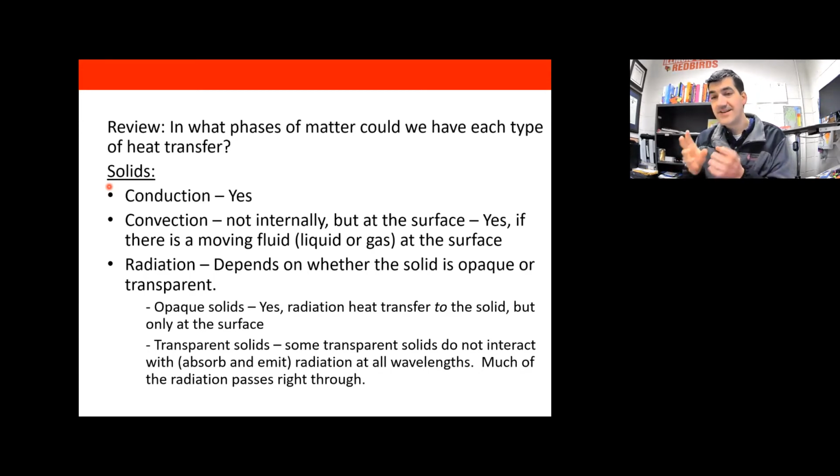Different solids interact with radiation in different ways, and this is largely the effort of modern window manufacturers: to try to only let the desired wavelengths through. You can design materials such that they absorb different wavelengths of energy at different rates. So you might design a window to absorb the UV light while passing most of the visible light through.